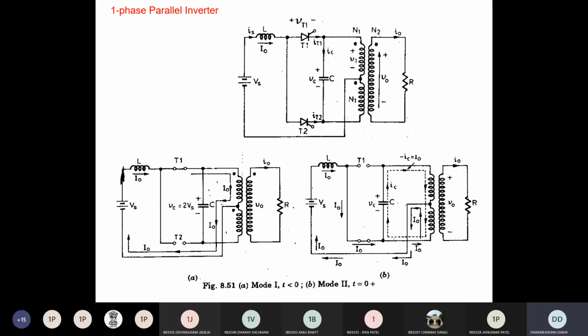All of you, I think, know this, you have studied it in control circuits: initial condition and final condition. Clear? So what is the initial condition? Initial condition means when you initially energize your inductor and capacitor. So what is the behavior of the inductor and capacitor when you initially energize? Open circuit or short circuit? Same way in the steady state condition. Steady state condition is the final condition. So once you provide continuous supply voltage and current to the inductor and capacitor, what is the behavior of it? Does it act as a short circuit or open circuit? Clear?